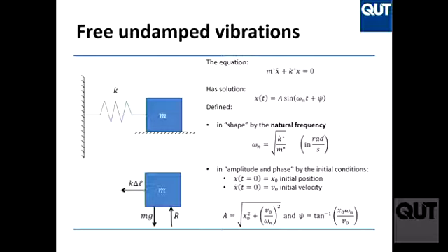I'll tell you why phase is not so greatly important. Do you really care where it starts? I mean, it's going to vibrate then, right? It depends on your definition of time, too. Where is time equal to 0? You have to decide what time equal to 0 is. I mean, is it really relevant? Think about an engineering case in which you are checking if your vibration is within a certain limit. Where it starts, not really relevant because it's going to go through all the positions anyway at a certain point, right? So phase is usually considered less important than frequency because frequency tells me something about how the motion happens, how fast the motion happens, okay?